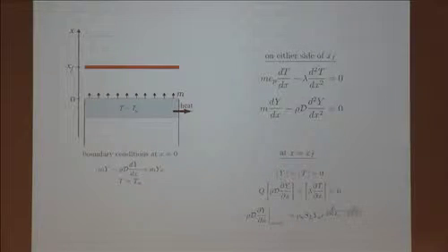Now, what are the boundary conditions? Well, the first boundary condition is that T is a constant, Tu. I addressed that a minute ago. And the second condition can be obtained from the general jump relations that we have derived across any interface, right? So the interface here is the top surface of the burner, and since there is no reaction at the surface, the relation that we have derived, I don't have to put it back because it's quite clear, is that the flux of fuel in is equal to the flux of fuel out.